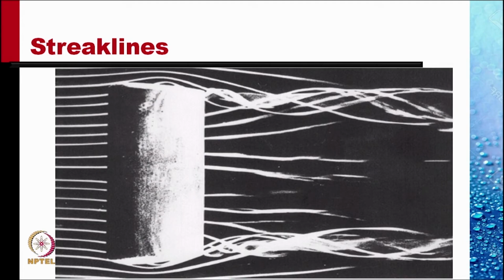And we see the streak lines do tell us how the flow is behaving. We see that the flow behind the aerofoil is kind of braided up into two braids of streak line, one at the top end, one at the bottom end. These we will learn later on are called the trailing vortices and are principally responsible for creating induced drag on this aerofoil.